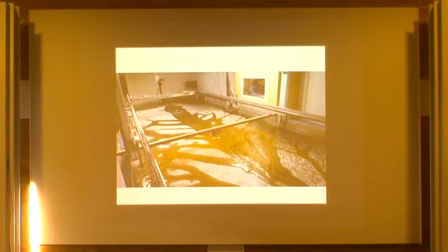There is no contact with ice, just something moving at a certain speed, generating waves. From physics, if you generate waves at the same speed as the waves propagate from that place, then the energy is accumulated, and the deflection of ice is also accumulated and the ice can be broken. So that is called the resonance method of breaking ice. It's more about technology, because the laboratory is ice technology. Everybody knows that it's possible.